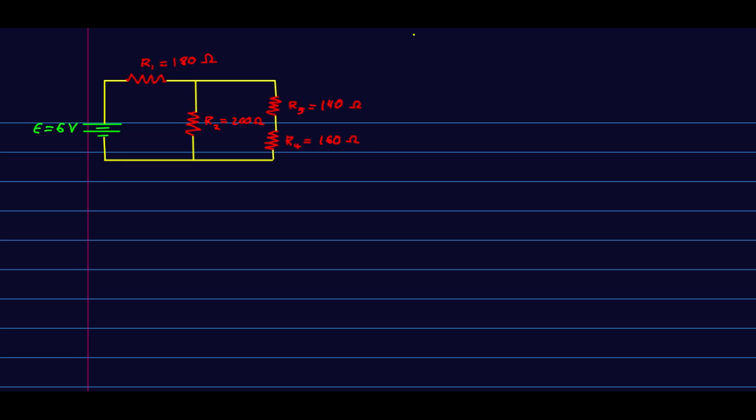But most students seem to prefer this method. So here you go. So we're looking for things we can reduce. And the only pair of resistors that's in a simple relationship here is R3 and R4. They are in series, and so I'll be able to reduce them to an RA. And we might as well do that. RA, the equivalent resistance of these, well, these are in series, so it's just going to be the sum, R3 plus R4, and so that's just 300 ohms.